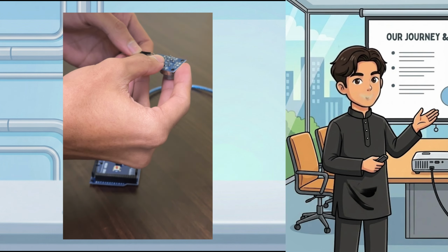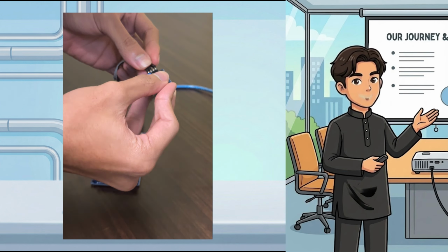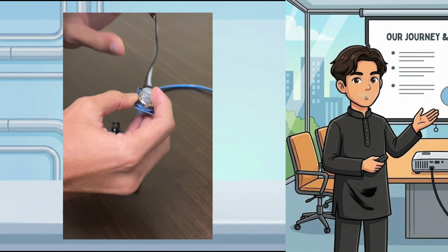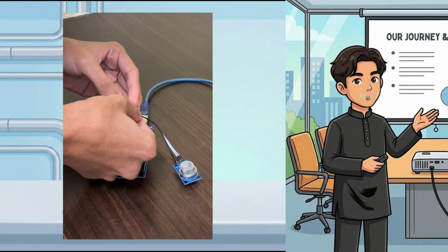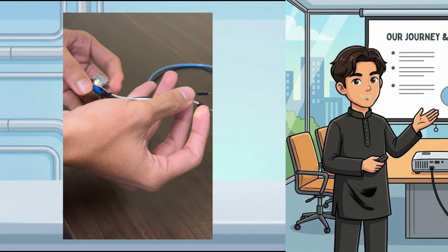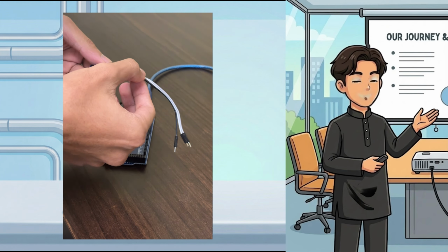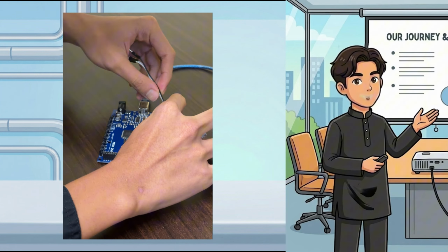So we connect the three ports on the MQ4. After that, we connect VCC to 5V.